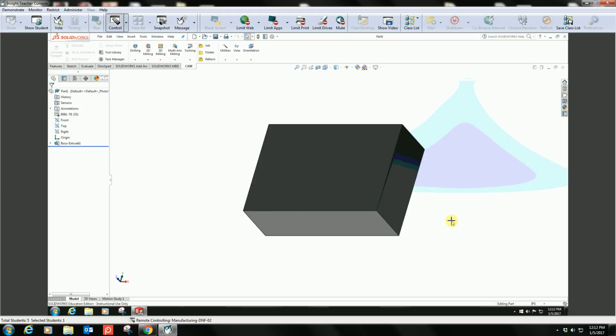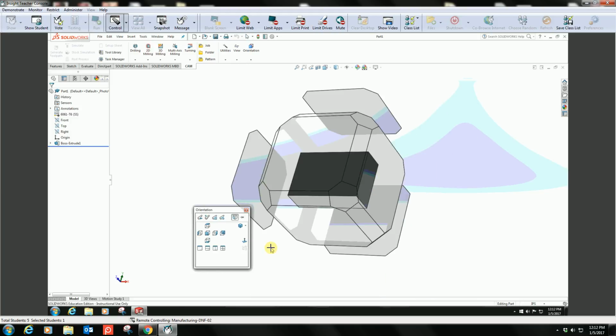Now I also have the ability to pick a view by clicking on the space bar of your keyboard, and when I do that, it comes up and it shows the cube. And if you hover over a face, it will tell you over on the right side. You can see up here it says front at the very top right corner. If I go over here to the right, it says right side. I can also do the same thing by going into this orientation bar. Notice I'm over the middle one. It says front, right, back.